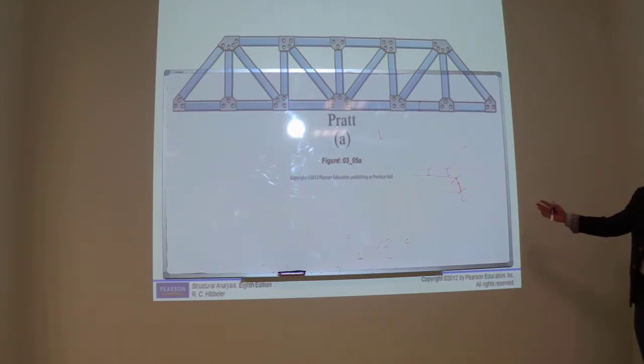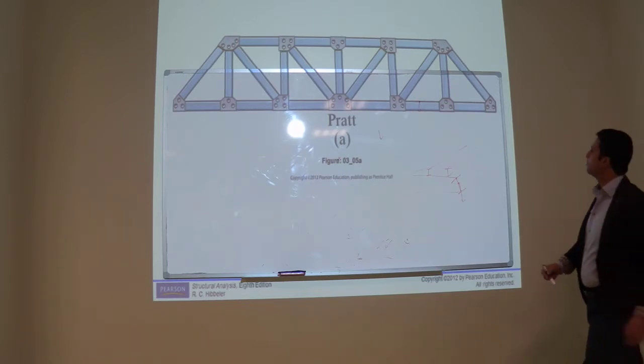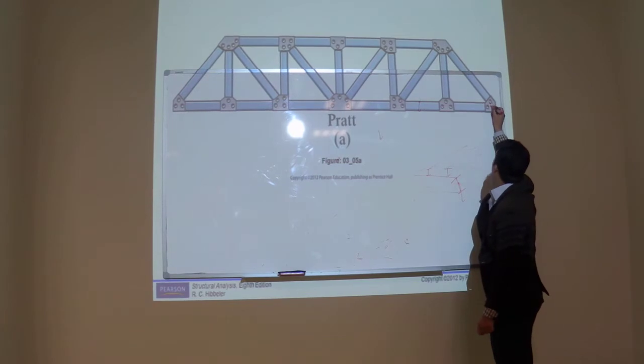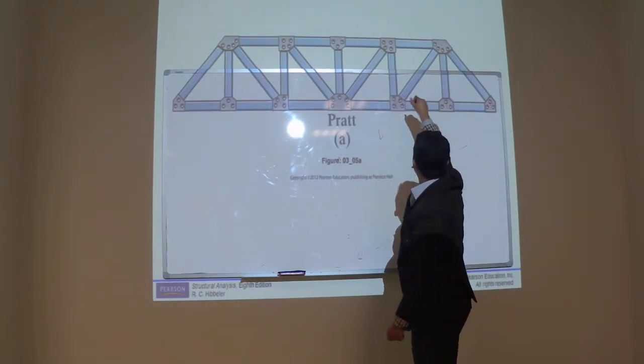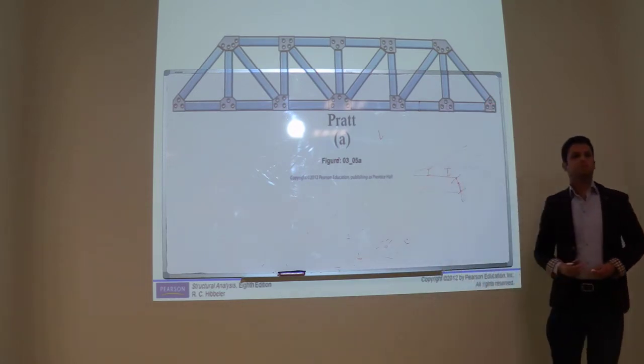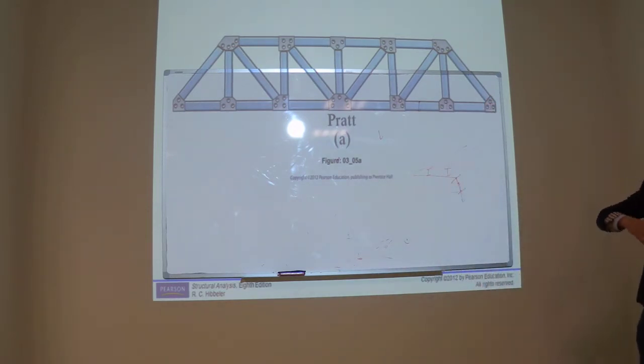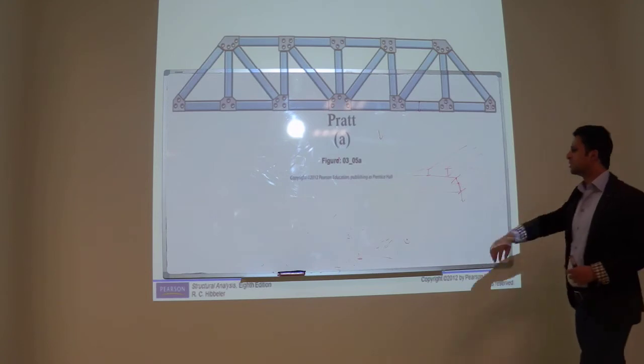I just taught floor beams. Floor beams are the beams on which the stringer is resting. Okay? So in this case there are 7 floor beams. One floor beam is here, going outside of the bolt, and in the same way they are connected on the other side of the truss.